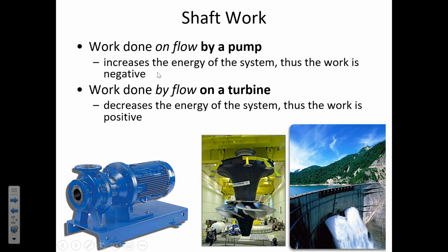In those two new terms in the energy equation, the watts that are being consumed by an electrical motor that's connected to a pump, for example, is what's adding extra head into the system. The reverse of that is that if you have a turbine, the fluid is spinning the vanes on the turbine, and then that is connected to a generator that's then producing electricity, is also going to have units of watts.